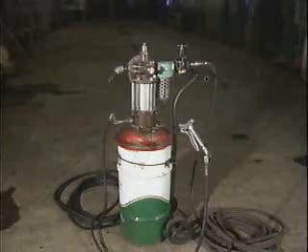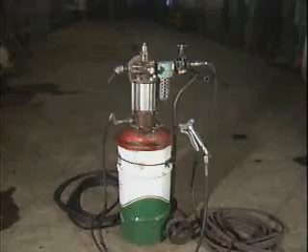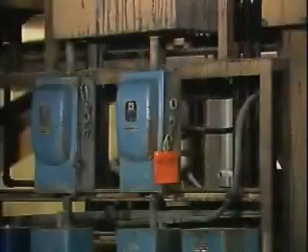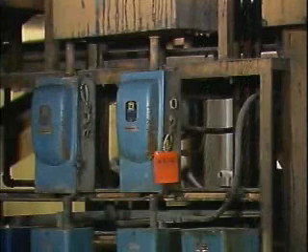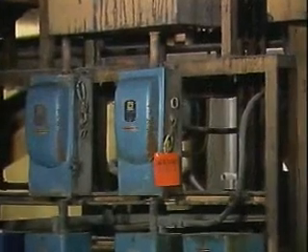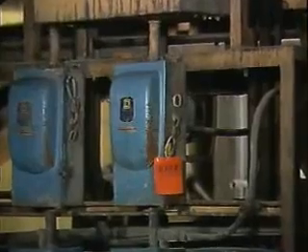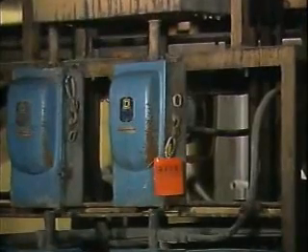In this part, we'll look at some typical examples of how to apply grease for proper lubrication of industrial equipment. Sometimes workers apply grease manually with a brush, clean cloth, or their gloved hands. The workers must use the required personal protective gear and make sure that the equipment is turned off, locked out, and tagged before they apply the grease.